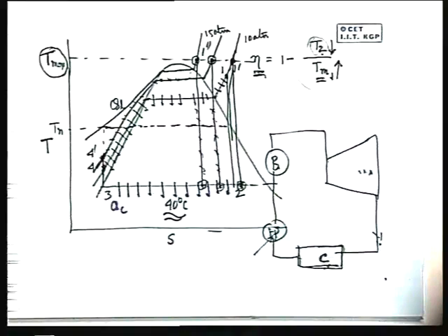It is clear. So to condense the steam at subatmospheric pressure, we will have to design a closed heat exchanger, and we will have to maintain a vacuum there by arranging something by which the air can be withdrawn from the condenser by a vacuum pump, to maintain a certain degree of vacuum. So therefore a condenser is required. Condenser maintains that, and there is circulating cooling water which is supplied to the condenser tubes, which takes the heat from the condenser. The condensers will again be taught in power plant. I am not going into detail of it.